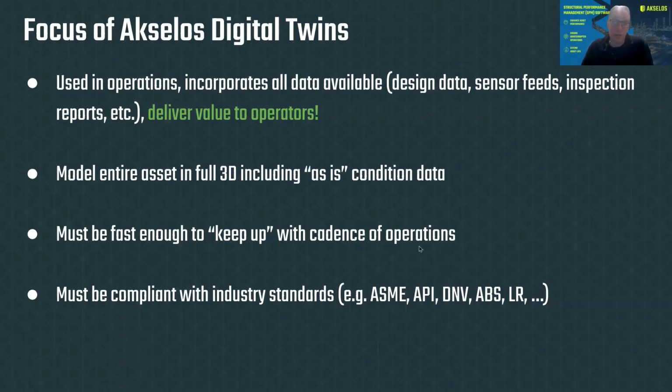So, we've spent a lot of effort making sure all our implementations are industry standard. And with our reduced order modeling approach, it builds on top of conventional FEA. So all these standards are built around FEA, finite element method. And because our RBFEA approach, as I'll talk about shortly, builds directly on FEA, our approach is also industry standard compliant. So that's one very powerful thing. But that is actually a very strong contrast with things like machine learning methods, which are not compliant with industry standards. So you have a very hard time deploying those kinds of non-physics-based methods in mission-critical situations.